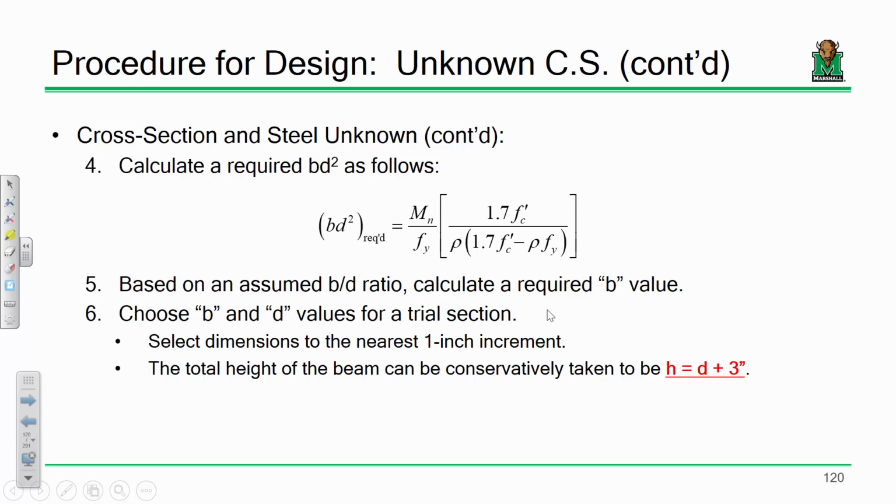That's a good question. The question was, would the cover change to affect the concrete requirements? It's not the concrete that's changing. It's the application that would be changing. Cover requirements are a function of what the beam is being used for. Cover requirements for a beam, let's say, inside a building are going to be different than cover requirements for a beam in a bridge over brackish water. You see what I mean?